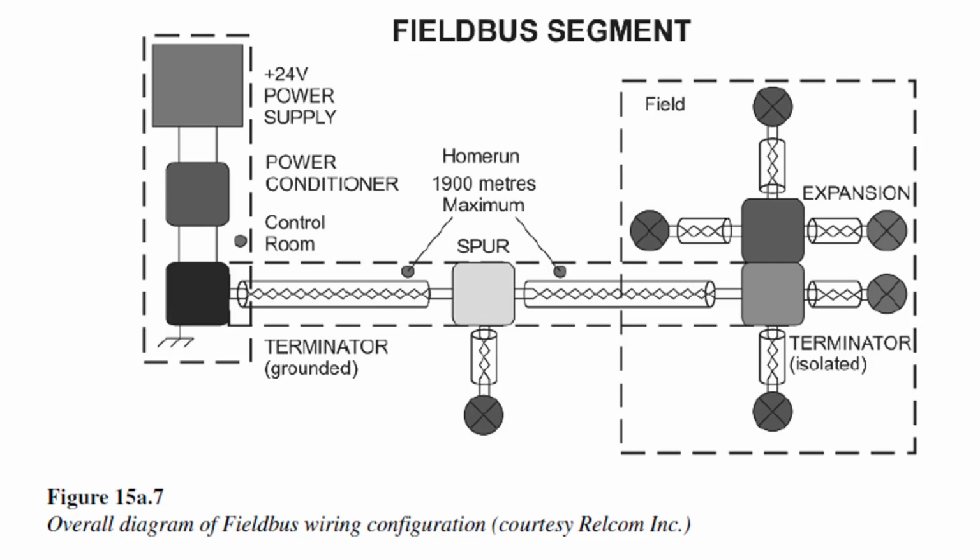Balanced transmission line. Other thing I'll say to you guys, my notes say you can't run 2 home runs and use them both for redundancy. That is 100% true. What you can do is run 2 wires and only use one of them and have a backup wire pre-run. If you think about it, right, you're running wire through conduit or over all this stuff from point A to point B in a building. Whether you want 1 wire or 2, does it cost you any more in time? Probably not much.